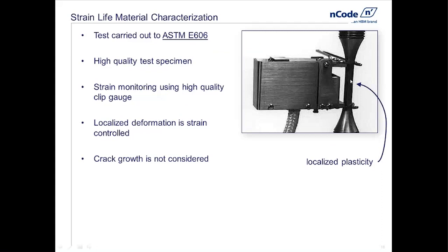You can actually just rubber band it on with dental rubber bands onto the part, so it's very easy to monitor strain in the part. That means then when we're cycling the test article, if we want to break this thing and see how big was the cycle and how long did it last, we can actually run this thing in strain control, which is great. Because remember, we said that strain makes more sense to understand microscopically what's driving a fatigue crack, what's initiating this crack.